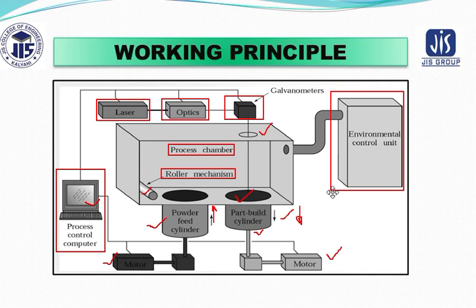So, where you are performing the sintering operation, it is also supporting the sintered portion. Now, another layer of powder is deposited. As I have told, this particular process is all about depositing layer by layer. So here you are depositing another layer of powder, and that is also in layer form. Now, this cycle is repeated again and again until you obtain the entire 3-dimensional part.